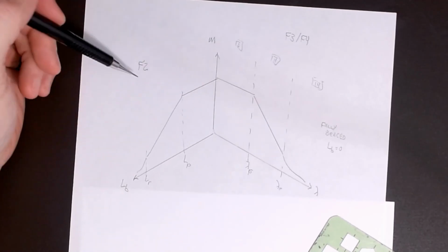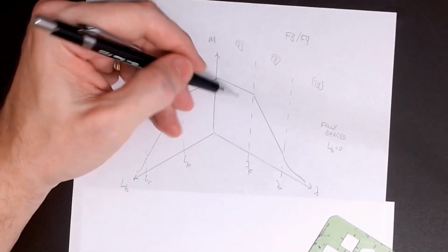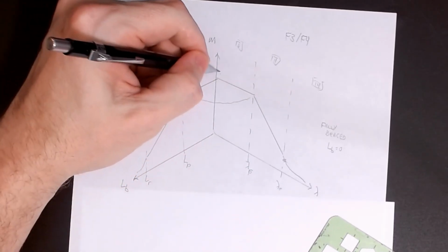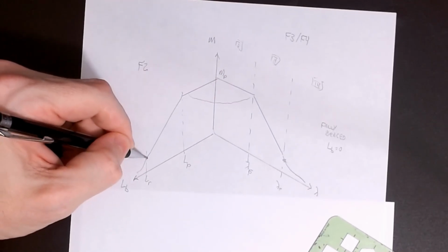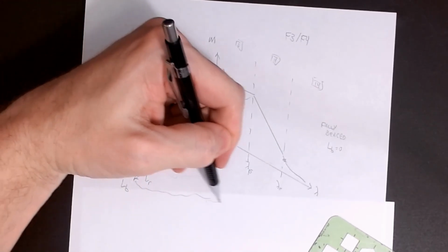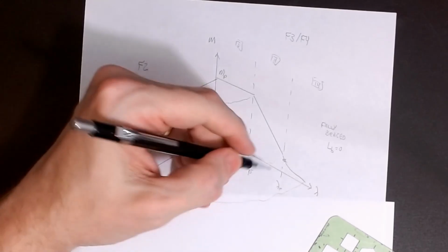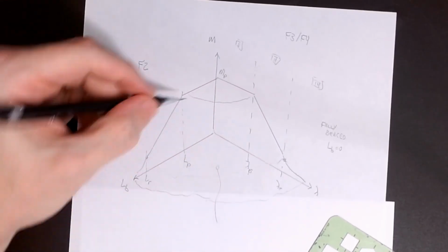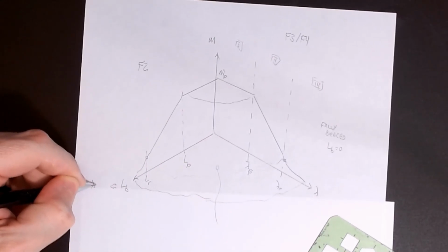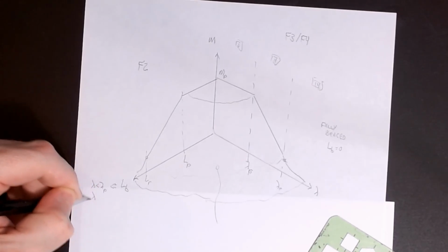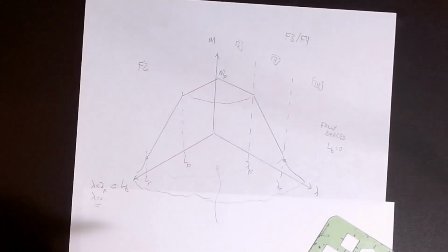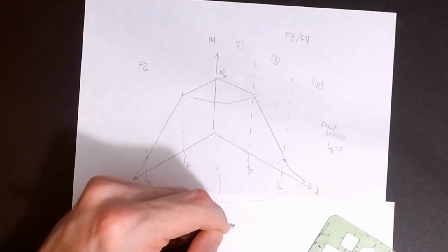But in reality, what happens if you're neither one of these pure simple cases? Well, this is actually a three-dimensional surface. There's my MR moment. This was MP, and it's MP on both sides. And this goes into some MR value, so you get a three-dimensional solid surface that runs around like that. Everything out here that isn't on this axis for LB requires that lambda is less than lambda p, or if you want to say that lambda is 0 for compact, you can. And over here it was LB equal to 0, but we didn't know the compactness criteria. Everything out here is called a plate girder.